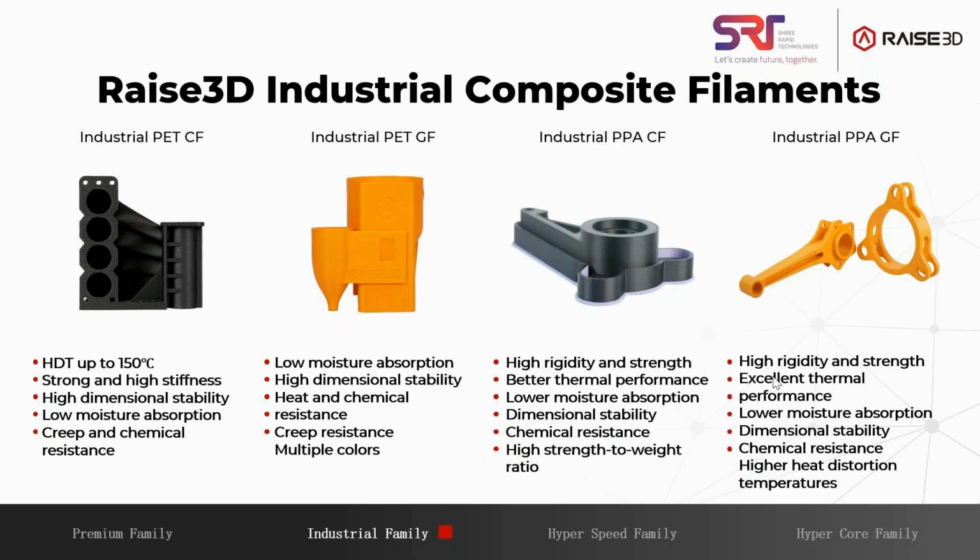Some of them are the PET-CF, PET-GF, PPA-CF. PPA is polyphthalamide from the family of polyamide or nylon. It's like the higher end version of polyamide.